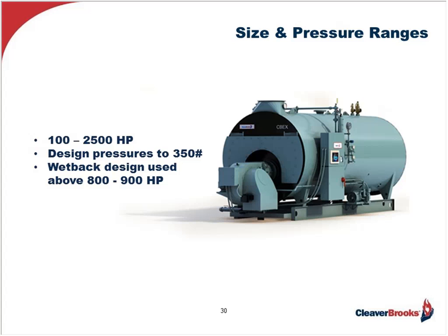And by the way, I also wanted to point out that the wetback design will be used in sizes exceeding 800 to 900 horsepower because anything above that renders that refractory-filled rear door just too big and heavy to maneuver.